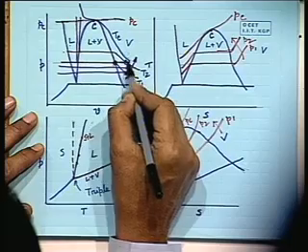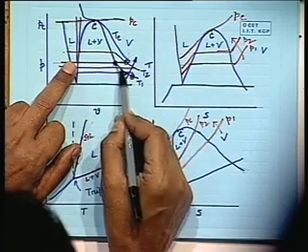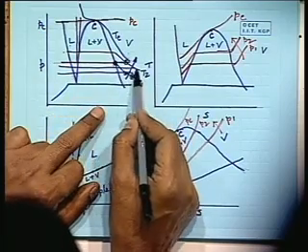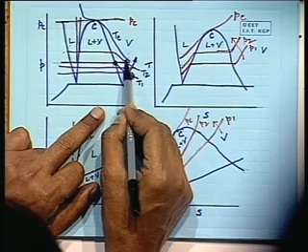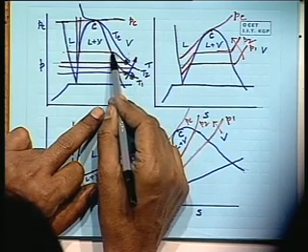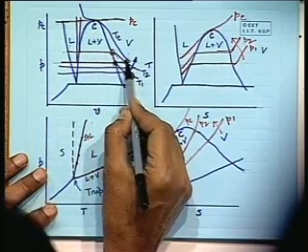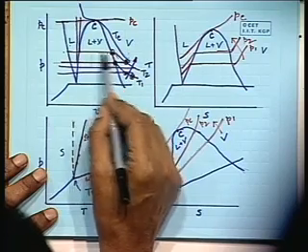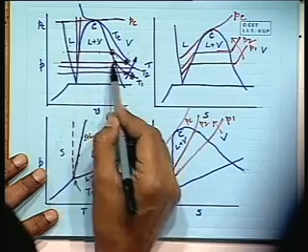Okay. Similar is the case at this intersection. That means this is 1 atmospheric pressure. Okay, and the corresponding isotherm is 100 degrees Celsius. This is 1 atmospheric pressure, but this is an isotherm at higher temperature. That means this is at a higher temperature, for example 150 degrees Celsius. If you compress it, that means it becomes at certain stage where this pressure will be the corresponding saturation pressure for this temperature, and it starts condensing. This is the liquid.